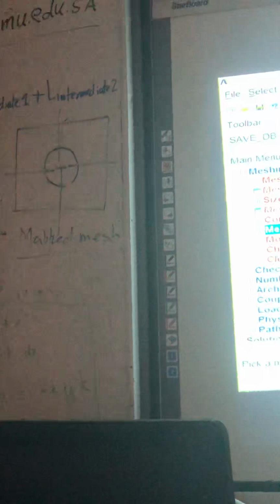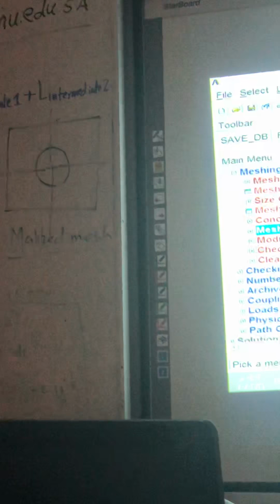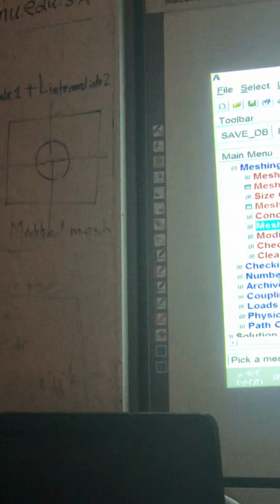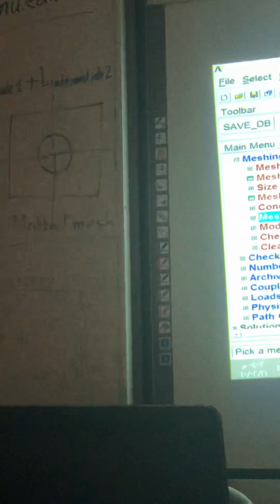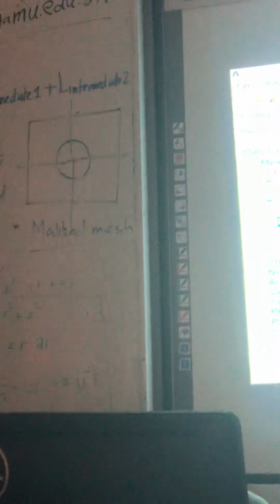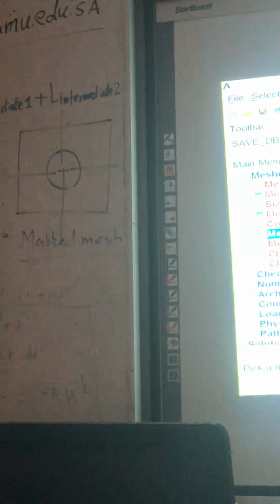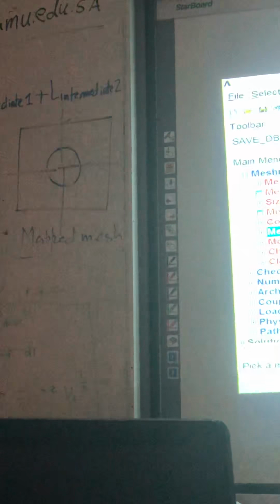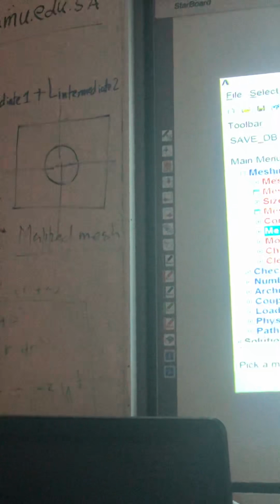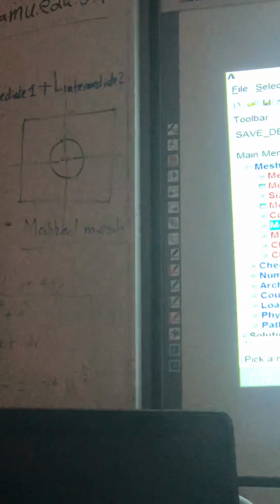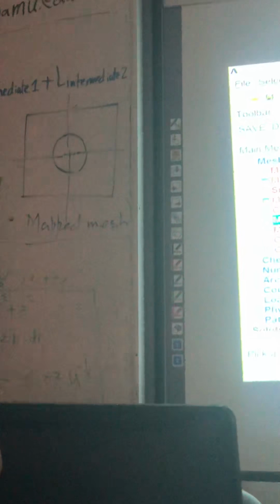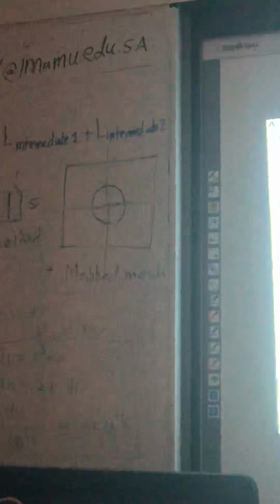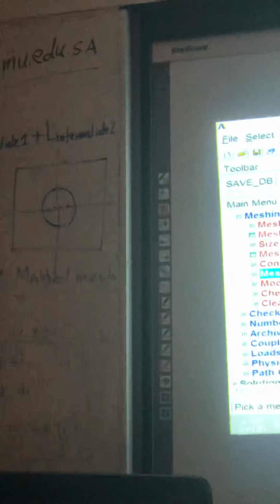For a truss, actually it's a bar element, right? So for bar elements we have 1D elements. This map mesh is for 2D elements or 3D elements. The concept of map mesh arises when you have a 2D element or 3D element, right? For a bar element it's a 1D element only. Doctor, should we include the symmetry problem here? I'm not asking you to solve this problem, just to discretize this problem. Okay.